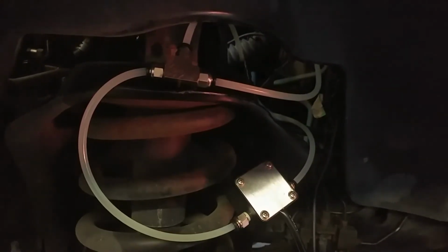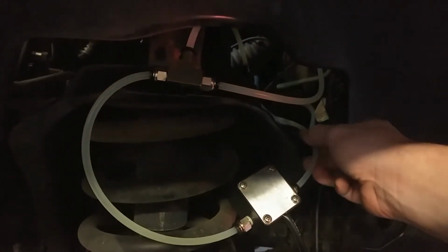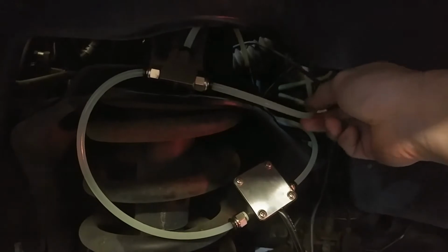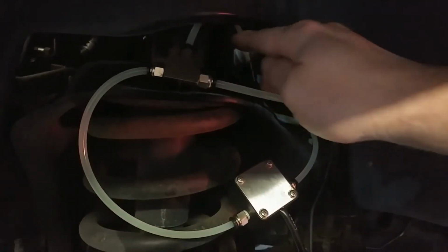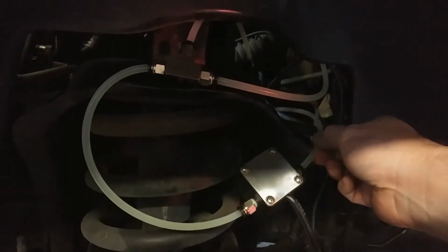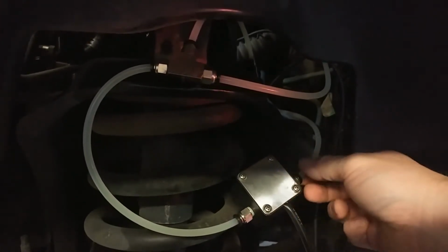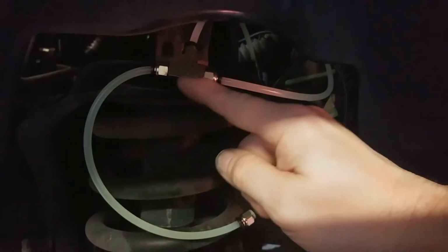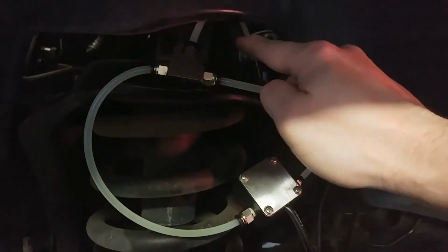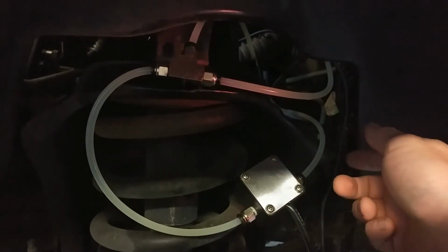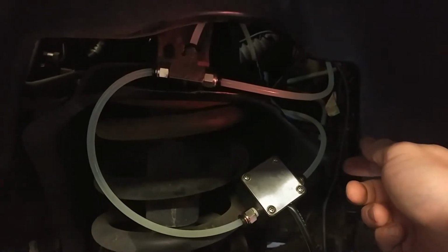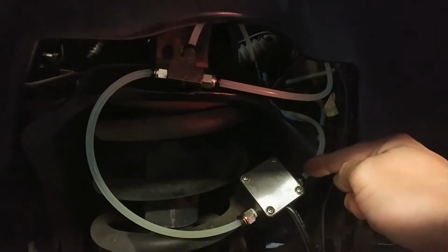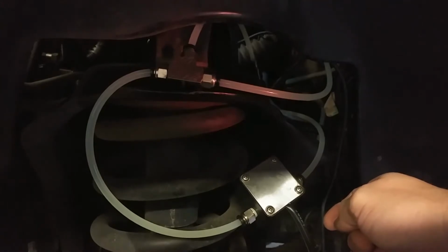Here we will show you the connections to the injector return line on the back of the fuel filter canister. This comes from the CP3 return. This is a return line that goes back to the fuel tank. As you can see, our inlet to the flow meter is connected, coming from the CP3 or the injector return line. And we go out and through this T connection and back to the fuel tank up here. So once we've made this connection, it's very easy, once we have done the injector back leak test, to switch this line with this line and do a CP3 loss test.